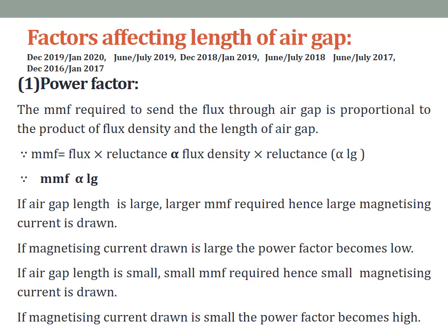Also, it may be possible to have larger air gap length. If you have precise manufacturing technique, the air gap length can be minimized. If there is no facility, if there are no precise manufacturing techniques or advanced techniques, the length of the air gap becomes large, because the rotor has to rotate in the air gap.